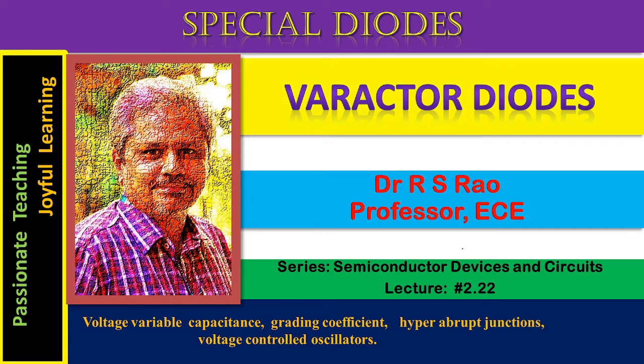Varactor diodes are semiconductor diodes. These are PN junction semiconductor diodes. They belong to the category of special diodes. They are used for their voltage variable or voltage dependent transition capacitance.